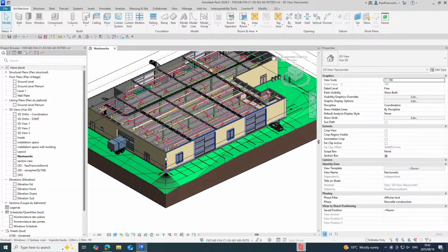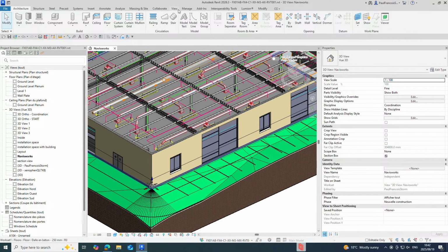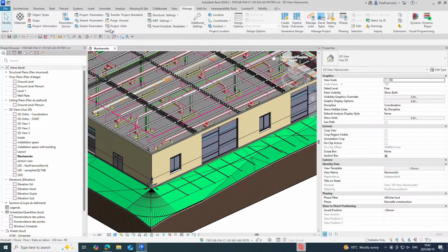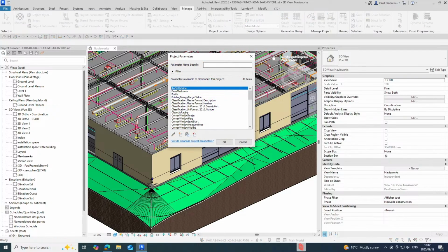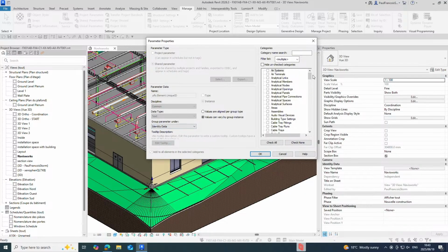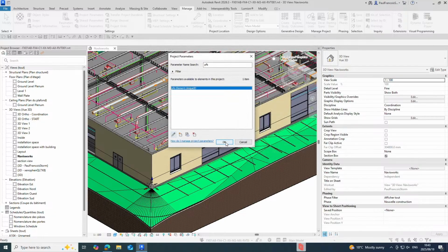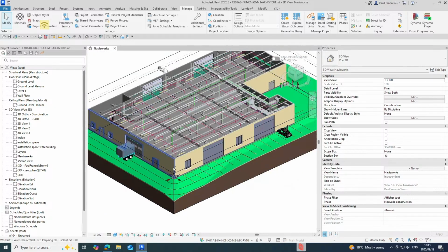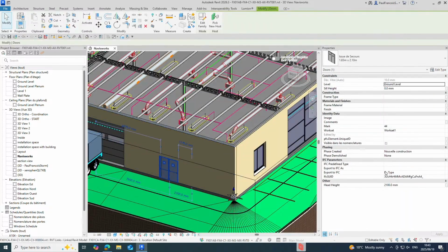You can import information in, or so on, and then if you attach it as a project parameter, then you can see there's the element. Let's edit that, and we see that it's applied to currently only Windows, but it might also be something like a door. All right, so each of the categories that you want to apply those globally unique identifiers to would work. And if you then click on the door, you can see that it's got an empty field over there.